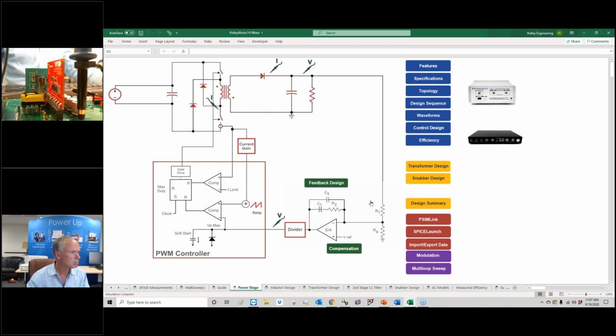They're asking what's the difference between this compared to frequency. There's no difference. I mean, a 60 hertz transformer and a 200 kilohertz transformer is the same process. You've got to obey the saturation thing, but a 60 hertz transformer is a transformer in general. It's not an inductor. Okay, we're designing for an inductor here, but we don't switch at 60 hertz for high density electronic power because the size is enormous. A 30 watt transformer weighs about 2 pounds. For this application, it's just a big thing, and it would cost more money than the entire switching converter would cost. But the process is the same.